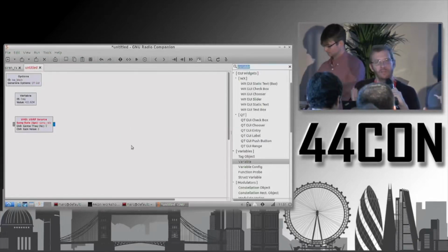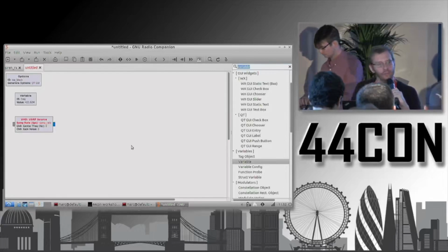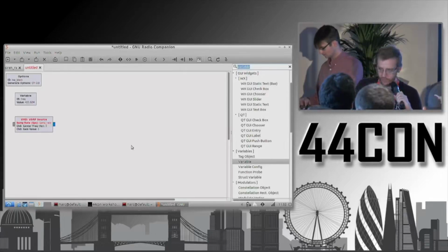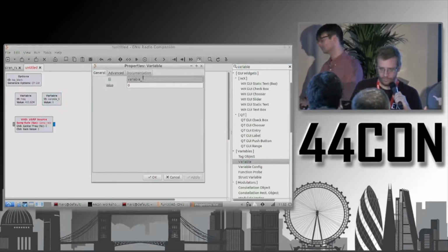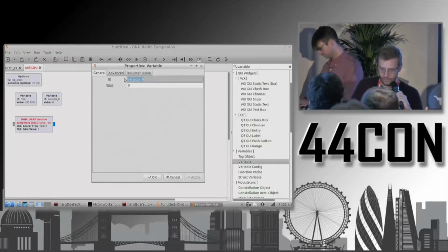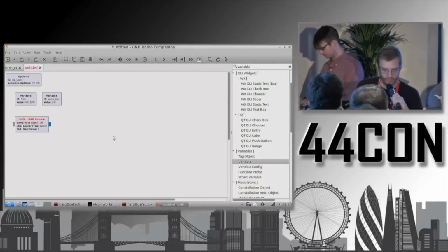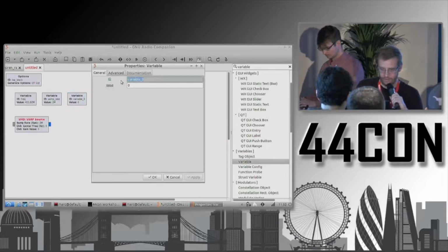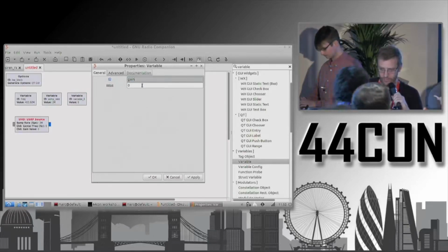The sample rate is the number of samples per second that the software-defined radio sends to the computer. With the RTL SDR dongles, those cap out at around 2 megahertz. So we'll do the same here. I'll set this to 2E6, so 2 megahertz. And then we'll set the gain on our radio here. I'll set that to, say, 20 decibels.